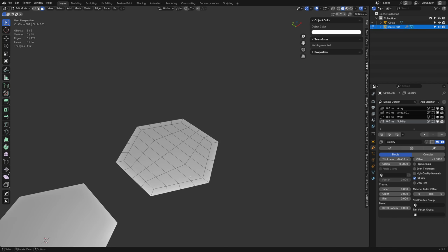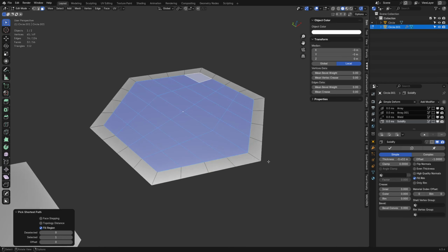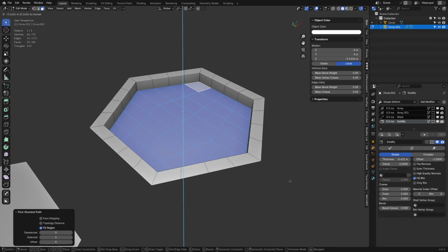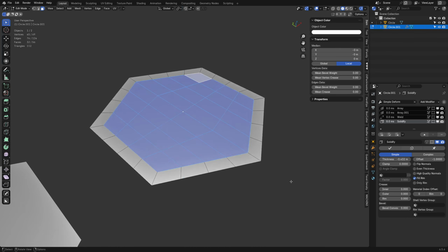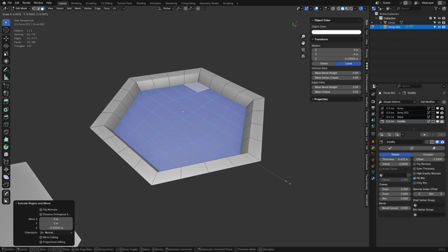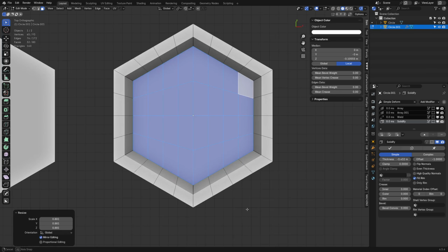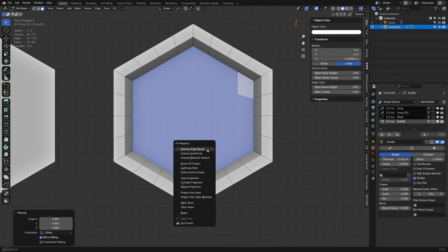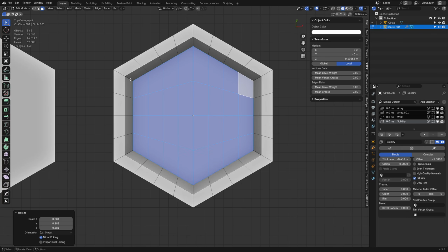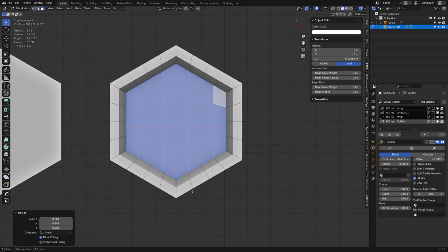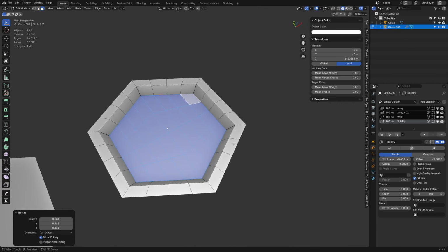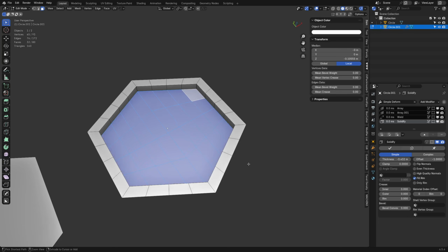Now, if we're going to UV map this, let's say we extrude down, that probably won't work out too well. Could extrude down and then scale it, and that would work out better. So we can UV map from the top using project from view later on. We'll still have some stretching to it perhaps, but it'll still have some texture on it that's not super stretched as if it was like this, which is almost impossible to unwrap in this current version of Blender at least.